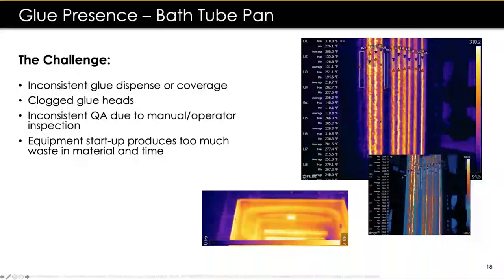So that causes their peel test or their pull test requirements, they would fail. And again, they produce 30 or 40 of these tubs and find out one fails, then they have to reinspect all of them. And once you do a destructive test, if you can't do leak destructive testing, as you guys would know, that product is then scrapped. So really what you do, you have to find the first and the last product that may be of interest of a potential failure, and you have to scrap that many units. And that was, again, very costly.